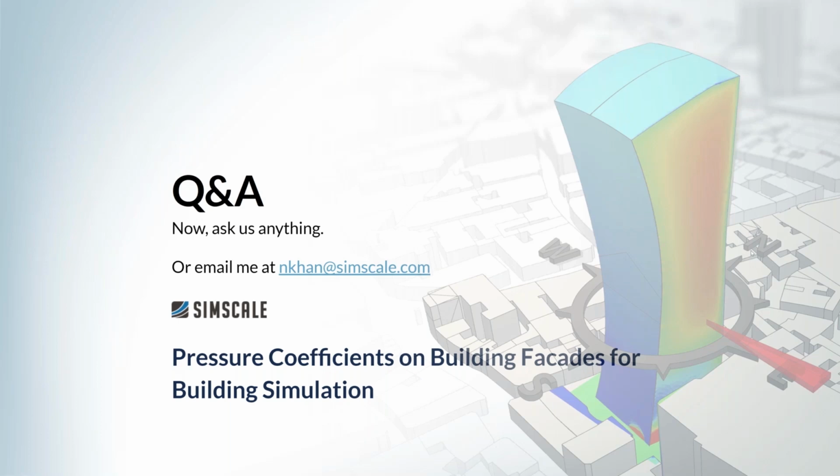So there's one question: how can one account for internal pressures, CPI? So this is basically at the heart of it, SimScale is a CFD tool. So there's various boundary conditions that can help you to set up the internal pressures. If you had openings as well, that's totally possible. This seminar was focusing more on the external wind pressures on the facade, which would really drive the airflow through a building.